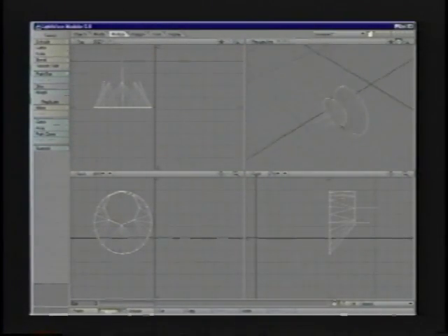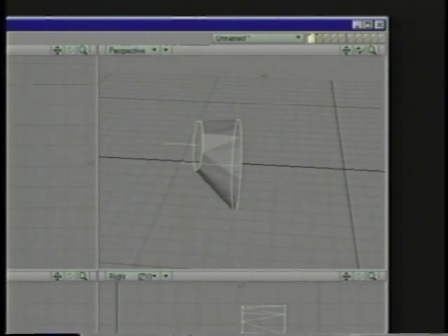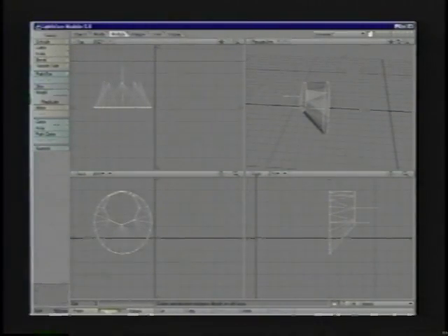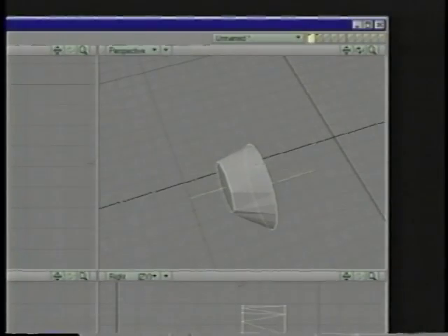Now if we look in our perspective view, again you'll see we're seeing inside of the geometry that was created. Now if we want to see outside, we could just flip this whole object, or let's undo the skin. I can go in and flip this first polygon so it's facing opposite of the second polygon, and then I'll do the skin again, and now you can see that we have a surface generated around the outside.